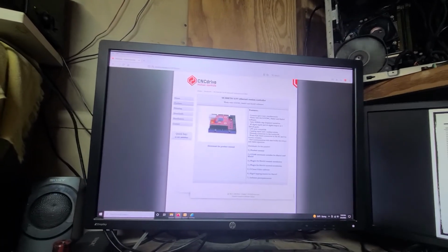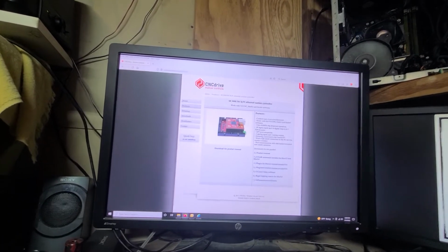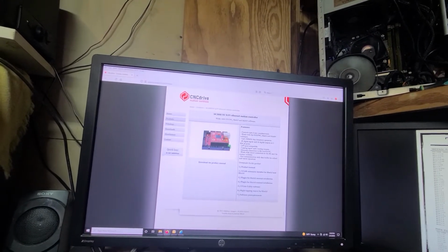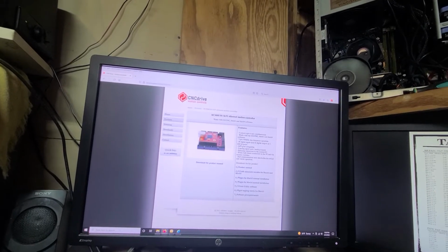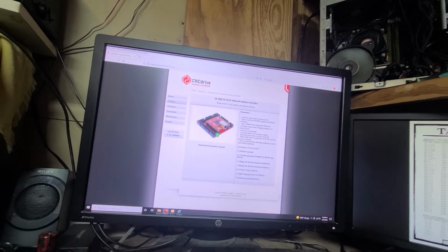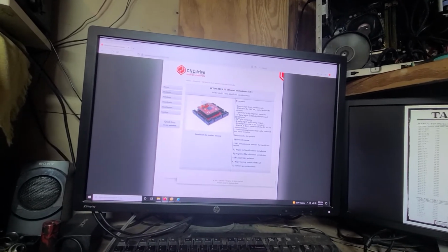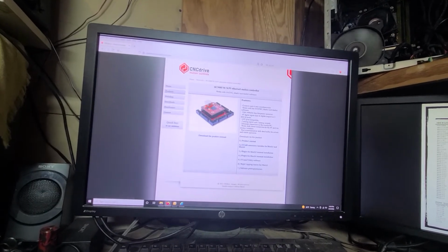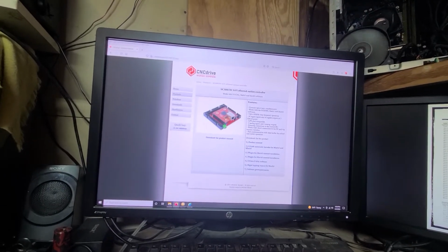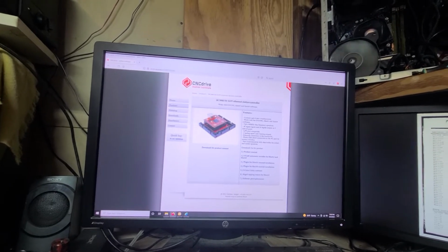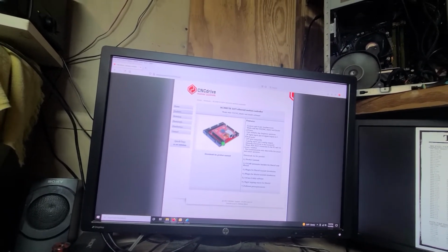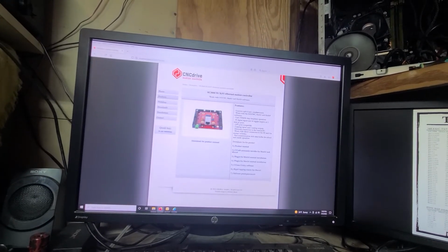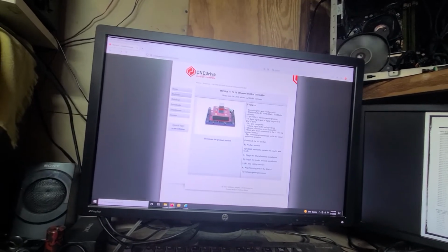So if we go through this process, and let's just say you have a Windows 10 machine, or I think even Windows 8 or 7 may do this as well, you go through the process of downloading the plugin file, getting it installed into the plugins folder, and then when you launch Mach 3, it comes back and gives you a couple of errors. One of them is that this plugin will be ignored. I don't remember the other ones. That's because you need the .NET 2.0 framework installed in Windows.